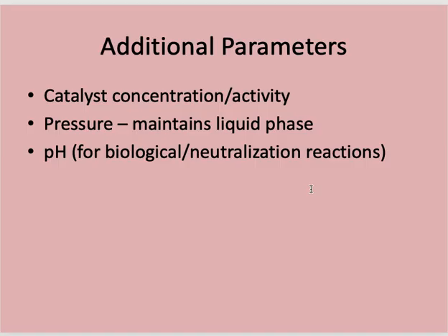The pressure can be positive or negative related to the design of the continuous stirred tank reactor. pH is one of the considered parameters. This is related to the biological industry. You control the neutralization and the pH by a pH meter, immersing the element of the pH meter inside this reactor.